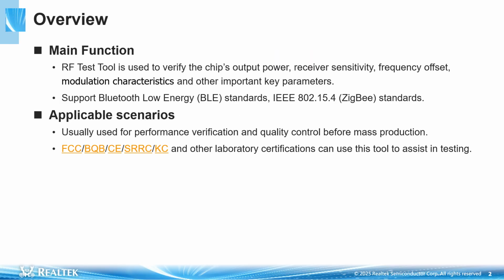First, the main function of the RF test tool is to verify the chip's output power, receiver sensitivity, frequency offset, modulation characteristics and other important key parameters. And the RF test tool supports two protocol standards: Bluetooth Low Energy standards and IEEE 802.15.4 standards.